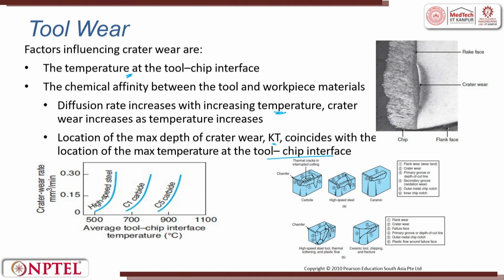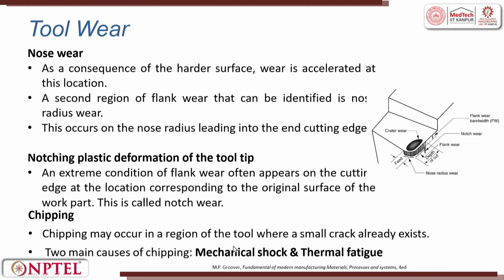When the machining happens, the chip goes like this. Here the temperature is maximum, and the crater wear is also maximum. This is the chip. So, crater wear with respect to tool-chip interface temperature, we have just plotted it here. The nose wear is also there, but it is very difficult to measure. As a consequence of a harder surface, the wear accelerates at its location.